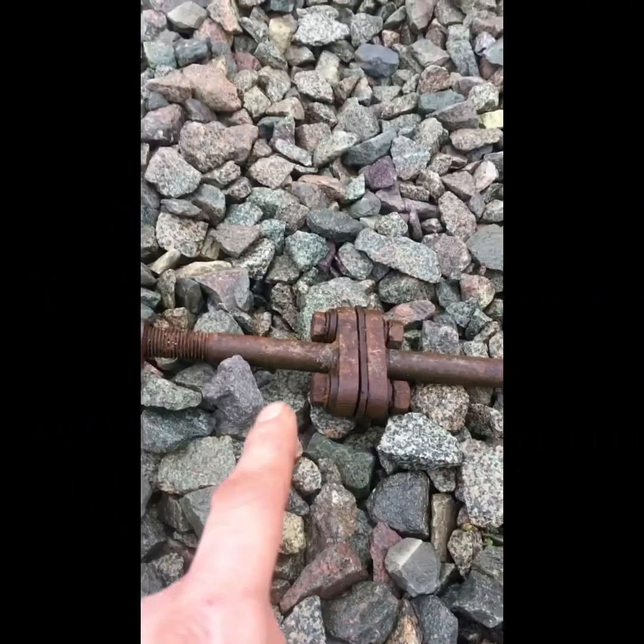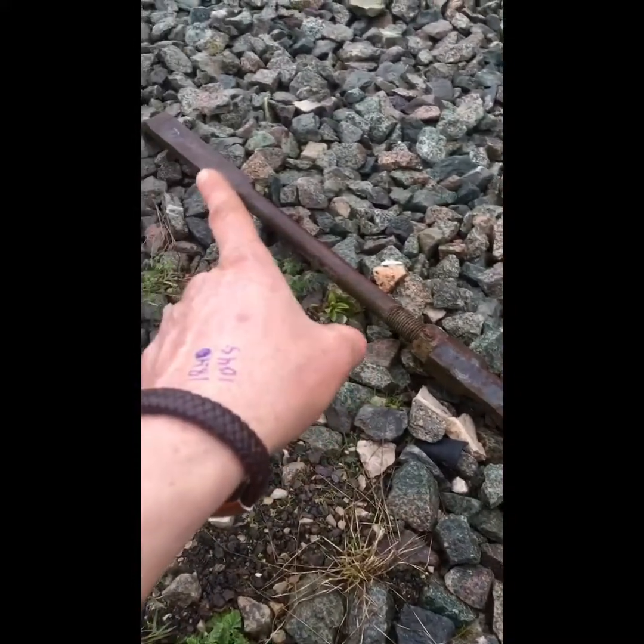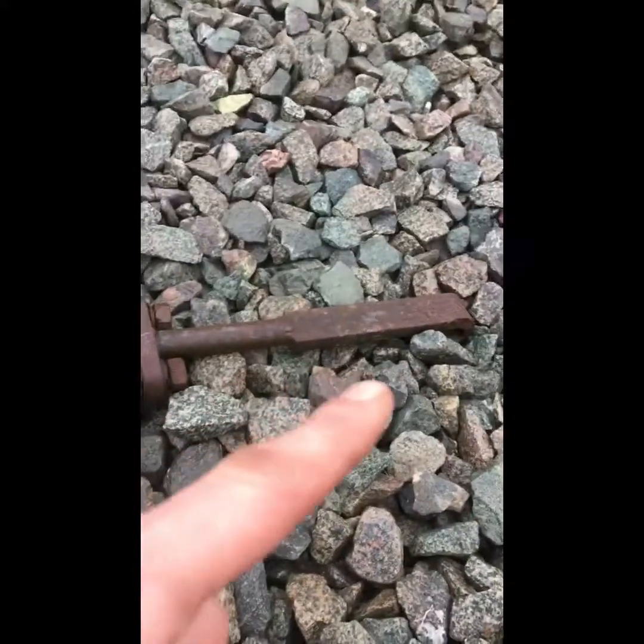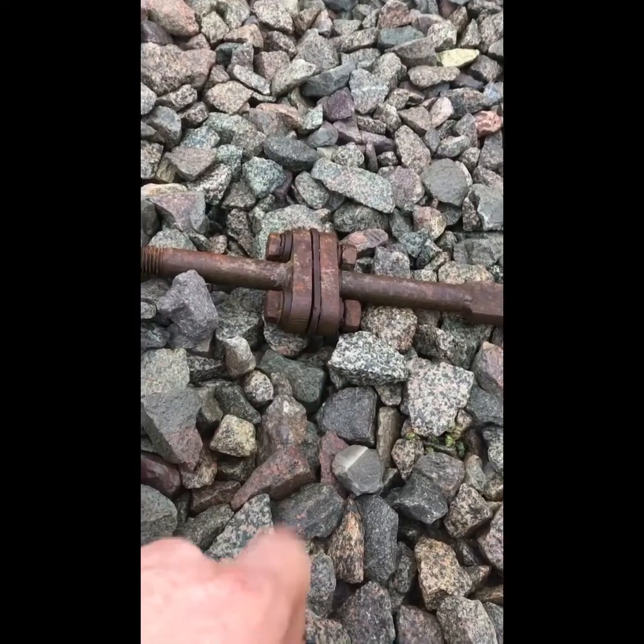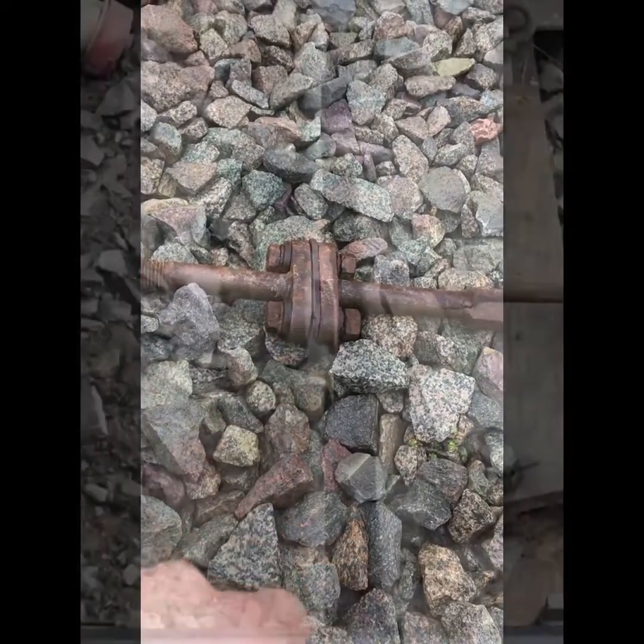As mentioned before, tie bars are the P-way used to bring the gauge in. This is a tie bar, has a clamp on one end, you put under the rail, clamp on the other end, you put under the rail. Should be insulated as well if they're on a track circuit, otherwise you will run the risk of putting a short on.